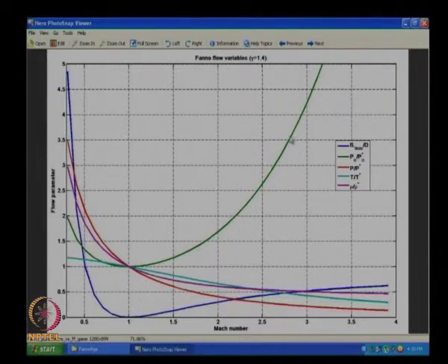If I pick a supersonic condition, I am going to have P naught dropping from, it's all arbitrary units, right, let us pick if my Mach number is 2.4, it is 2.5 times P naught star, and by the time it goes to M equal to 1 from 2.4, it is dropping to equal to P naught star. But in the subsonic case, of course I cannot get an exact equivalent here, there is less space, only between 0 and 1 I have values.